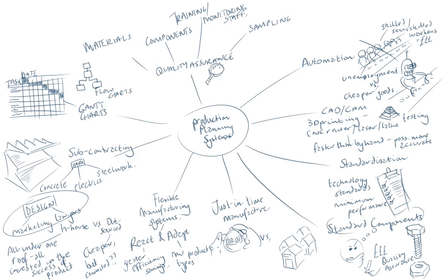So you need to test whether or not the materials that are coming in are good enough quality for your products. Similarly, components, for example, standard components: are the standard components themselves of a suitable enough quality? So for example, your nut and bolt might be made out of steel, but were you expecting it to be made out of a higher tensile steel or a higher carbon content steel? Is this steel that they've given you much more like cheese? It's kind of just not up to scratch.